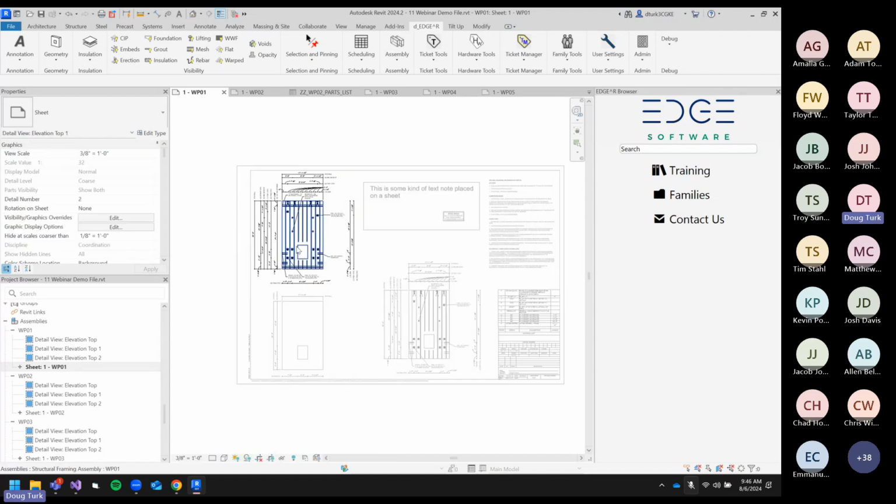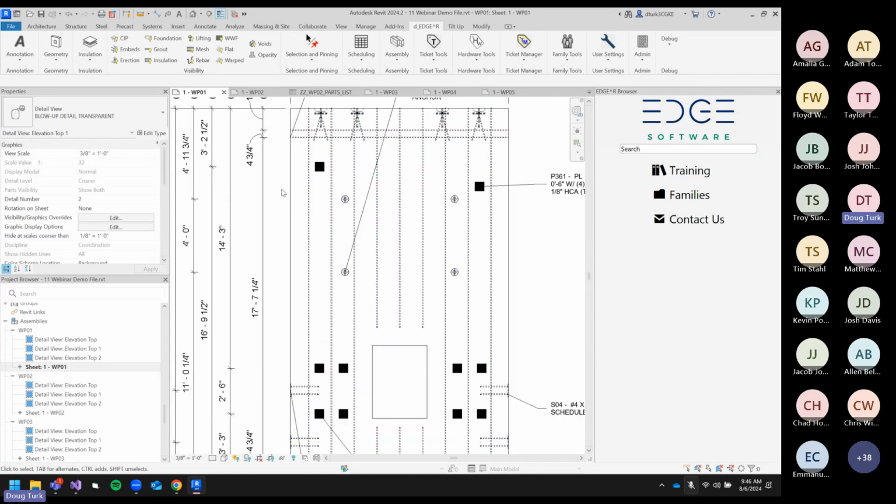One other important thing to note with the clone ticket tool, and why I mentioned that if you're doing this from a shop ticket created using edge tools, things will be much simpler. When we copy dimensions to elements in the piece, we are only looking at dimensions pulled to edge dim lines for the elements in that piece.